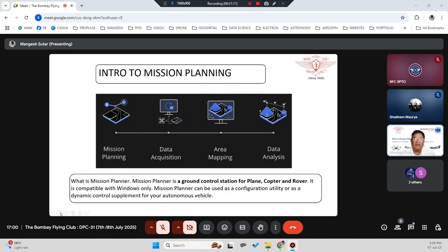So when you are flying, normally our flying is RPAS flying. When we are flying a drone for some kind of mission, we need to have a ground control station. For example, you are flying an agriculture drone. In that scenario also, it is not advisable to fly an agriculture drone in a manual way, because you will not use the drone's endurance capacity efficiently. Where you need to cover 1 acre in 8 minutes, in that 8 minutes you will hardly use I would say 10% of your drone endurance capacity.